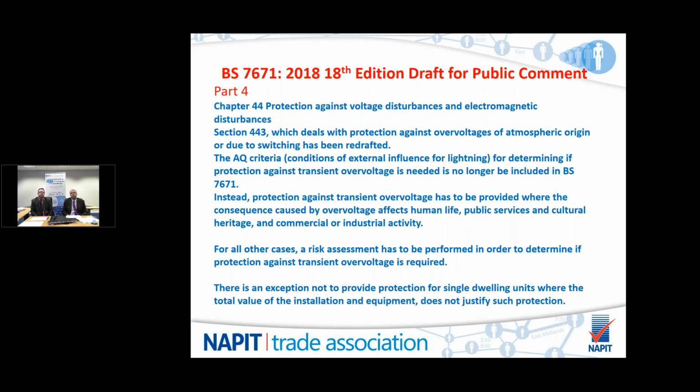Instead, protection against transient overvoltage has to be provided where the consequence caused by overvoltage affects human life, public services, cultural heritage, and commercial or industrial activity. For all other cases, a risk assessment has to be performed in order to determine if protection against transient overvoltage is required. The only exception to this, and to not provide protection, is for a single dwelling unit where the total value of the installation and equipment does not justify any such protection.